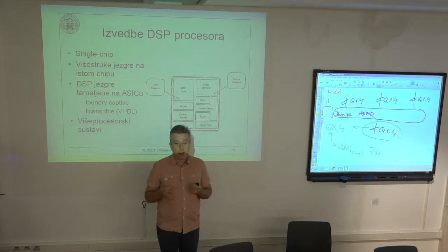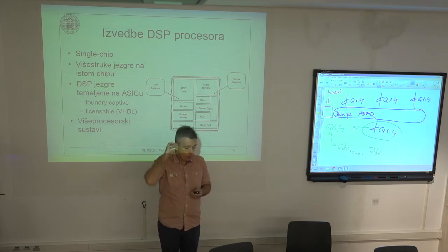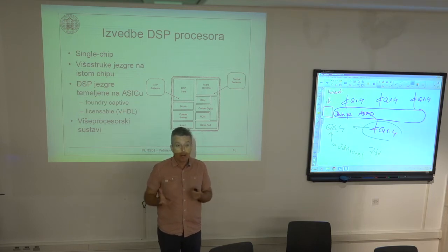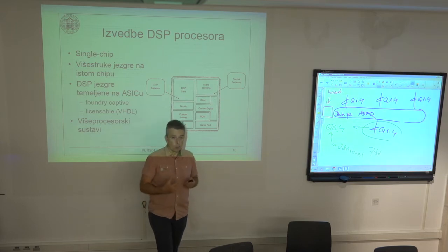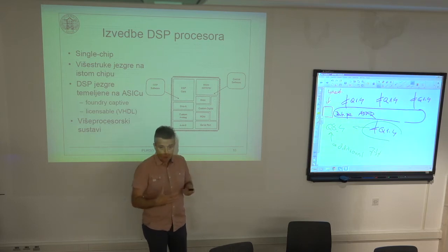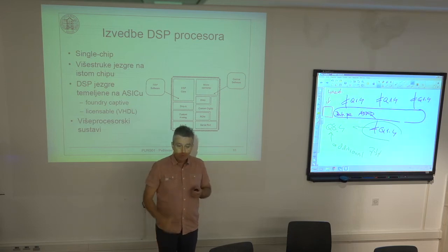And this configurable hardware, these FPGAs, are almost ideal to implement such software-defined radio. Okay, so all of this architecture shares the common idea with DSPs, but they are not a single chip CPU. They are dedicated hardware that is then designed, controlled by some state machine or by some host CPU, but it is not a standalone CPU.